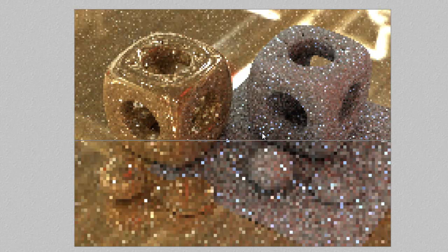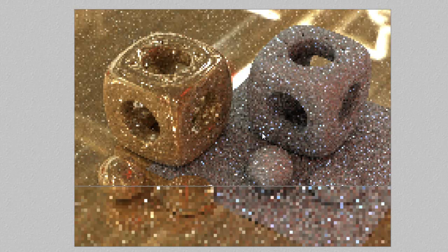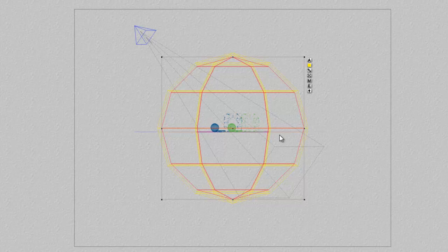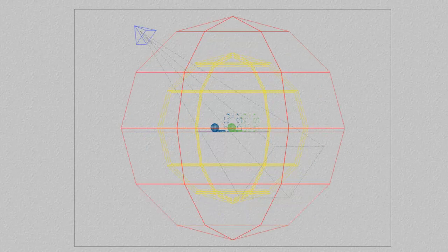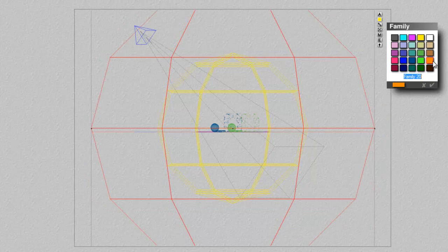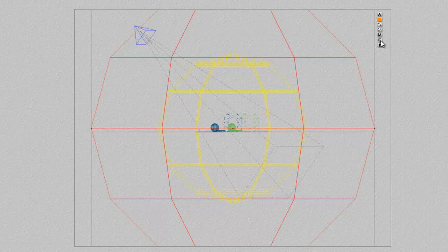Okay, we'll put the backdrop in. We're not producing any HDRI effect from the backdrop, but because the transience method is seeing the backdrop and it's high dynamic range and coloured, we're back in trouble with the noise. However, we can use this gel light source method again to save us from this. So if I Control C, Control V, and create another light source that's outside everything. I'll make it a bit bigger to make it obvious. I'm going to change the family so we can see that it's different.